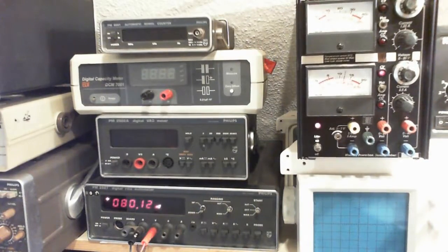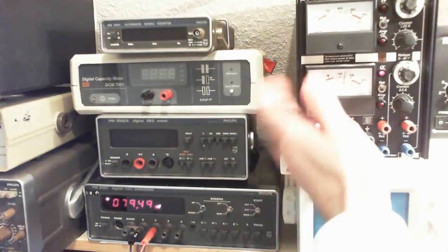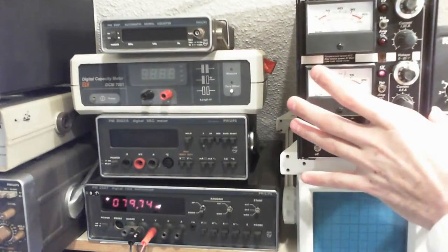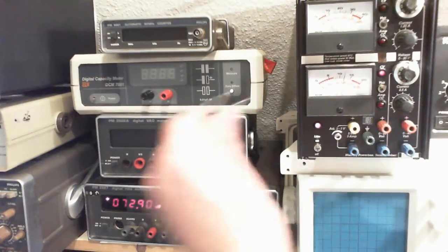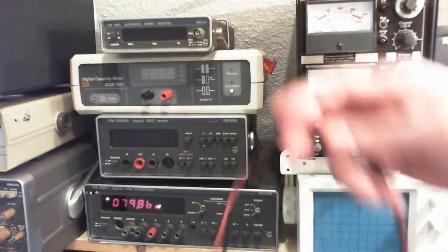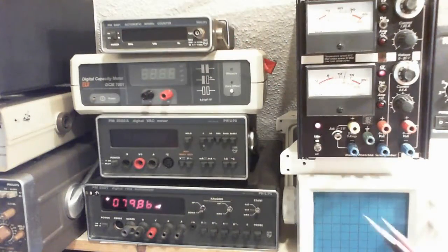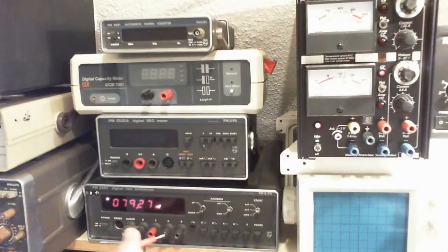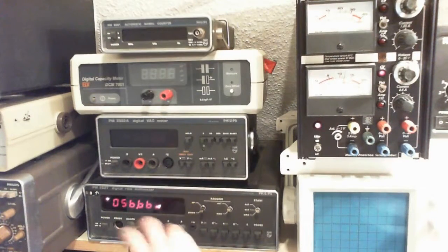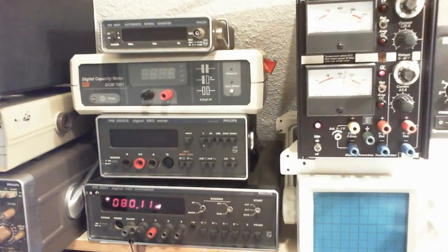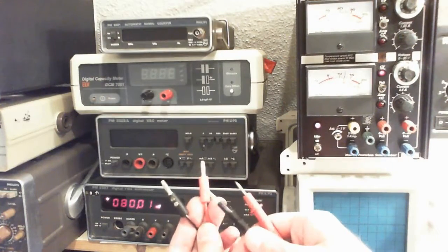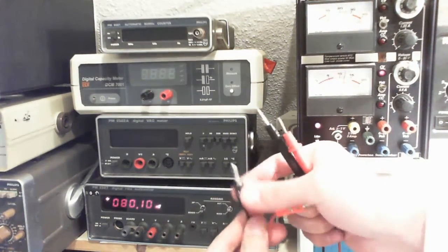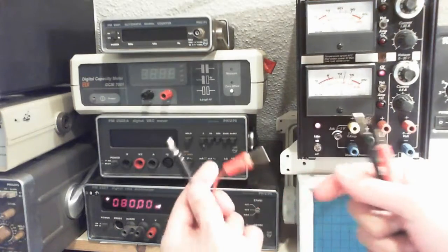And if you want to measure, for example, volt DC, which is the output of this power supply, you can set it to volt DC, and then you have, for example, these probes over here. So you connect the probes to, for example, 0, which is common between these three, and then the other one to volts. And you can see that the probes are color coded, meaning that you have a red one and a black one.